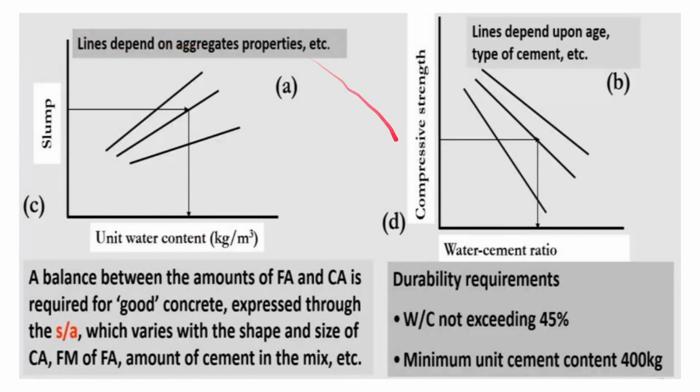If you remember, rounded aggregates had the maximum workability, so that means the maximum slump. Similarly, compressive strength is mainly dependent on cement, because the more the binding, the more the bond strength, and the higher the compressive strength. As much good binding as it is able to make, the higher the compressive strength, and that basically depends on the water cement ratio.